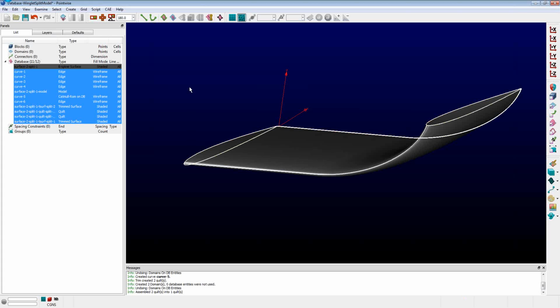The reason is because we don't allow those changes to propagate through that hierarchy. So if you're at the model level and you do those trimming operations, this is to prevent you from destroying your geometry. If you're at the model level and you're doing these trimming operations, eventually you're going to do enough trimming operations, if we allowed this to propagate to the base geometry, that the original geometry would get flushed out of the undo stack and you would never be able to recover it.